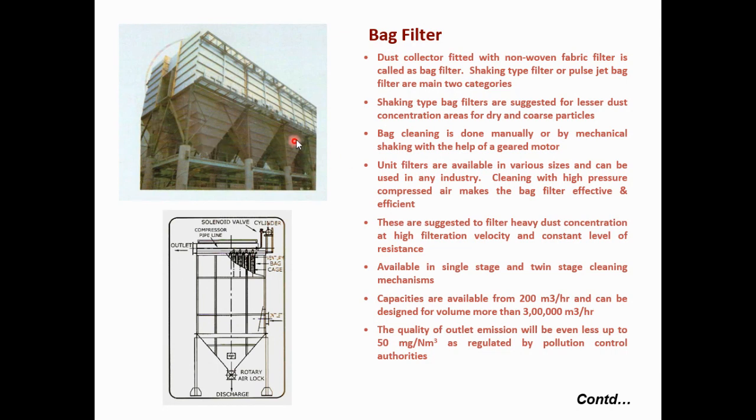Shaking bag filters are suggested for areas with lesser dust concentration and for dry and coarse particles. If the dust particle size is larger, then these shaking bag filters are suggested. Bag cleaning is done manually or by mechanical shaking with the help of a motor. If there is a mechanical arrangement, as I have said, it may be used. Otherwise, you have to apply some labor to shake the bag filter periodically.